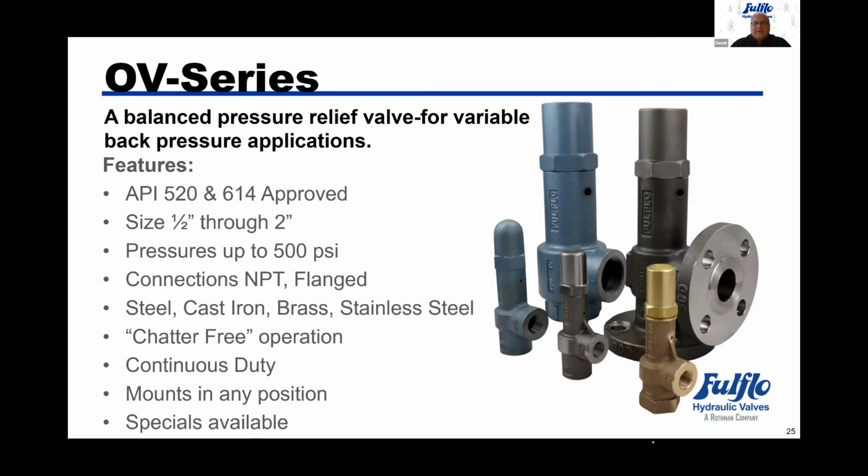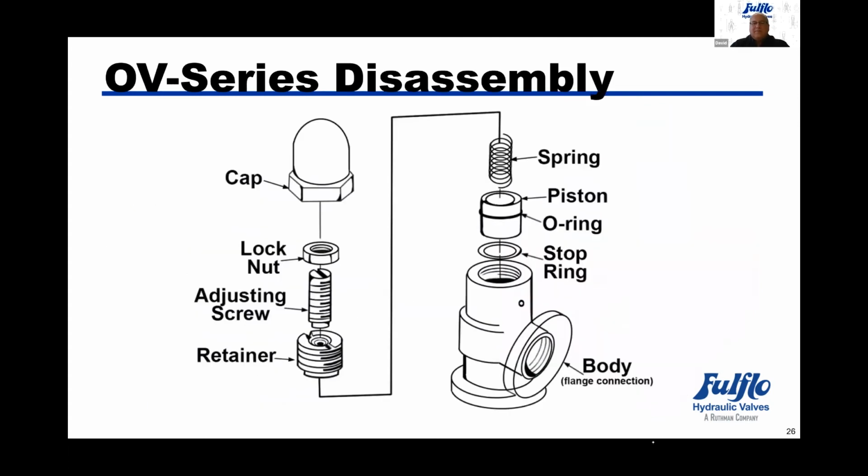So as I was saying, on the body itself, there's a small hole. That's the breather hole. It's the vent as the piston would slide up and down inside of the valve. The pressure would exhale the air that's inside the spring chamber as the valve is opening, and it would inhale air as the valve is closing. The O-ring there would prevent the fluid from getting up into the spring chamber.